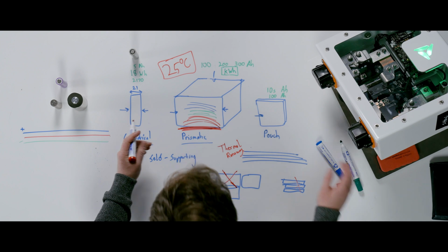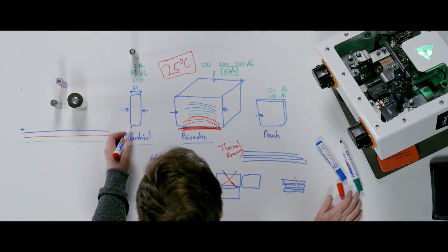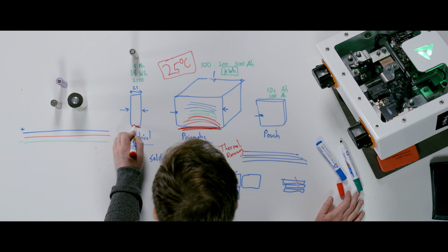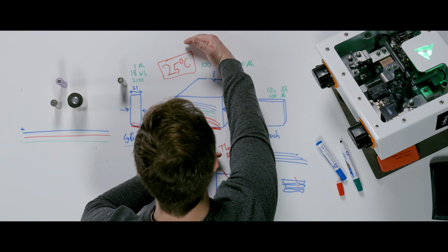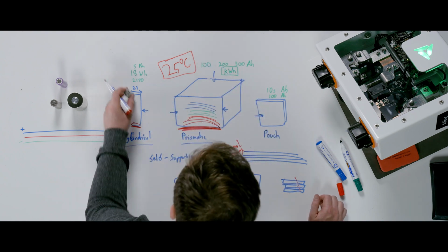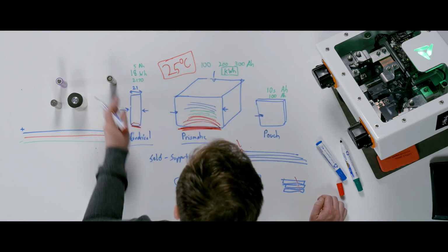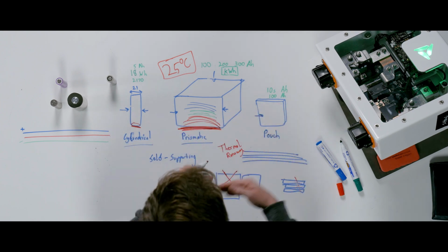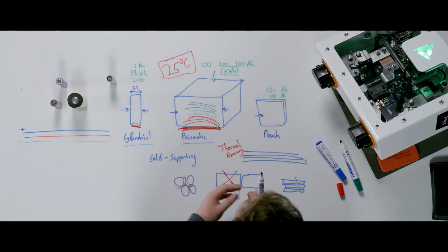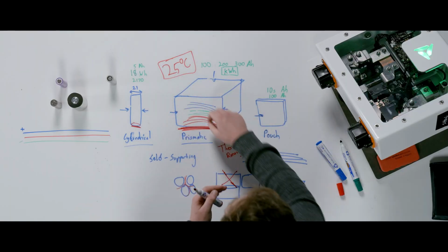With the cylindrical cell, because it's physically much smaller, it's much easier to do it here because the gradient on something that's this size versus something that's almost as big as this table is much, much lower. So cooling smaller cells is a lot easier. And also, when it comes to pouch cells, you have a similar type of issue to cool practical cells. So big cells, harder to cool, harder to get the energy in and out of the core, especially when the heat is internally generated, because these internal heating effect results in very strong temperature gradients inside of the cell.